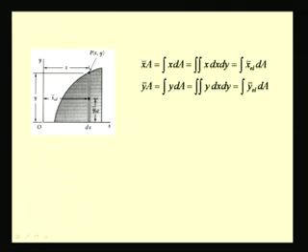Here you see one example where we have this curve whose equation is known, and we are interested to find the centroid of this area, that is the area under this curve. So, let us take this thin element, which is a vertical strip whose centroid is located at y bar element and x bar element for the axes OY and OX.